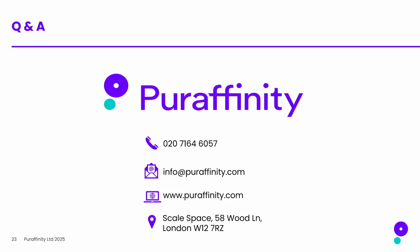How is Puretech G400 affected by heavy metals in water? It depends on which ones they are, but one of the advantages that we have, for instance, is with metals like iron and manganese. With some of the other media out there, the iron and manganese has to be removed first. We don't necessarily have that issue, because our material can be backwashed. So when you backwash it, you're not just disturbing the mass transfer zone of the material. You can backwash things like that off. But for other metals, one of the first things we do on any application is send out a questionnaire to get an idea of what's in the water and work with our technical folks to make recommendations if we think something needs to be treated prior to the G400.